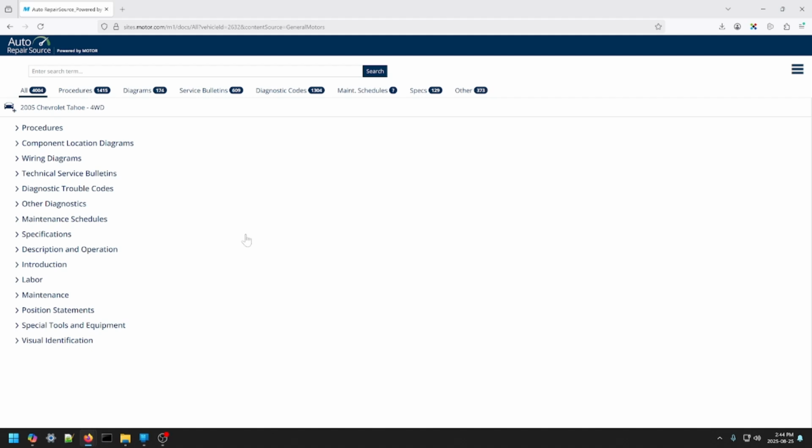And so this is not so much about me actually going through all of those steps and showing you exactly how I repaired it, but more about how I used this information to assist me in the repair. So when there's anything electrical and there's no check engine light or DTC code, it's time for me to go to two things: how the whole system works, description and operation, and then the wiring diagram. So I want to go to description and operation first to get an idea.